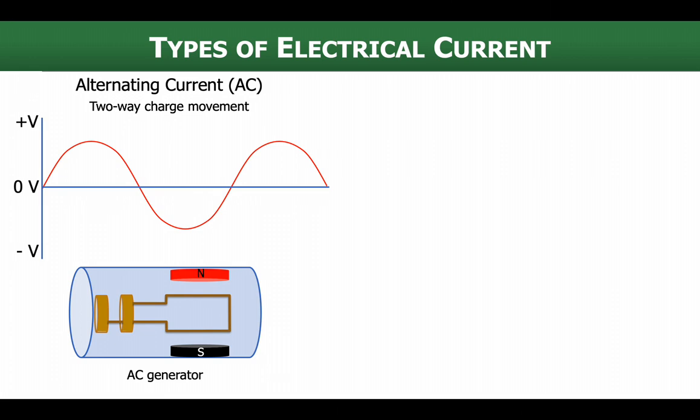A sine wave. That spinning action in the electromagnetic induction creates this sine wave where we build a voltage, and then it drops and switches directions and we have voltage down here, and then it goes back again and on it goes. That's our AC sine wave. One of those cycles, starting at zero, going to a positive voltage, back to zero, down to a negative voltage and back, that's what we would call one cycle. 50 hertz, 60 hertz, different parts of the world have different cycles for their electricity, but that would be one cycle there. So we're really showing 1.5 cycles in the total graph.